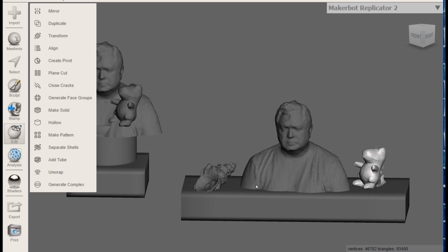And when it's big, like say the bottom of this base, or even this bottom sort of plinth that's holding things, you'd find that it's very easy to do that because it's just layer on layer on layer on layer. But if you have a layer here like my chin sticking out, it needs to prepare for that layer way down here at the bottom, and it will add scaffolding, which is just material that is meant to only get it up to this point, where then it uses good material to build the rest of it. And it will need to do that for any overhang. So this is an overhang. These little arms are overhangs. There's going to be a lot of overhangs on a piece like this, right?